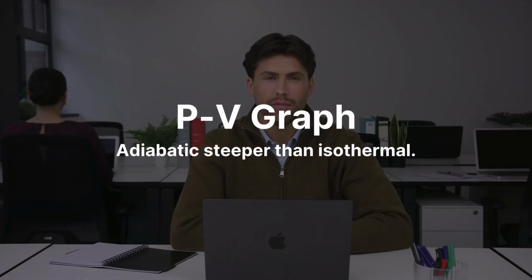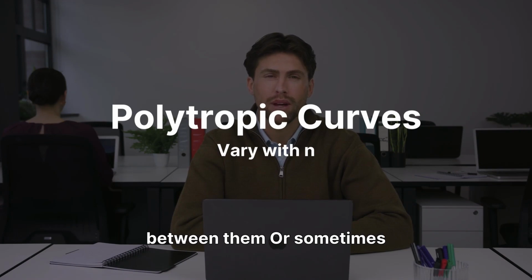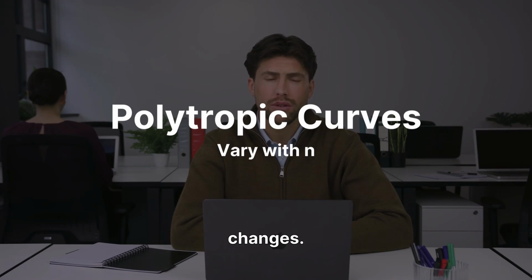Imagine a pressure and volume graph. The isothermal line is smooth. The adiabatic curve is steeper. The polytropic curve lies between them or sometimes outside. The curve changes because the value of N changes. Higher N means steeper curve. Lower N means flatter curve. This shows how flexible this process is.